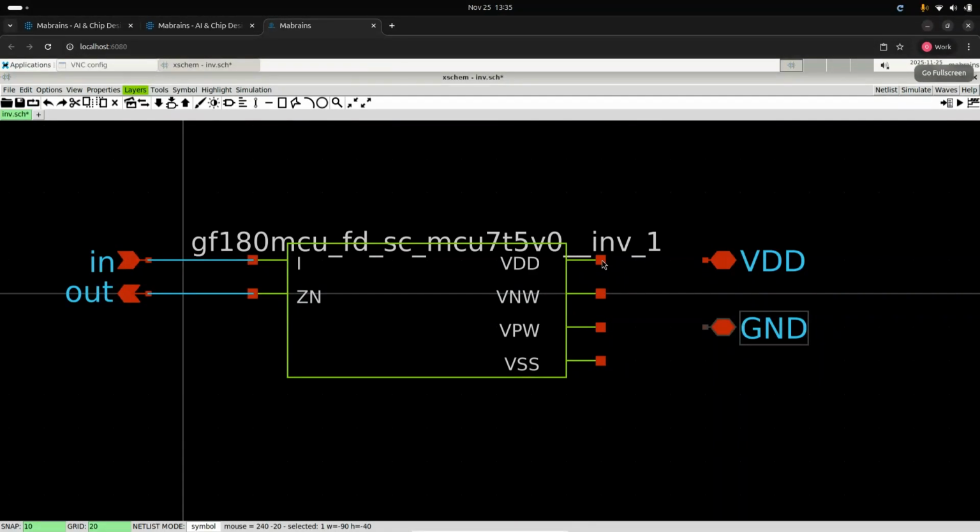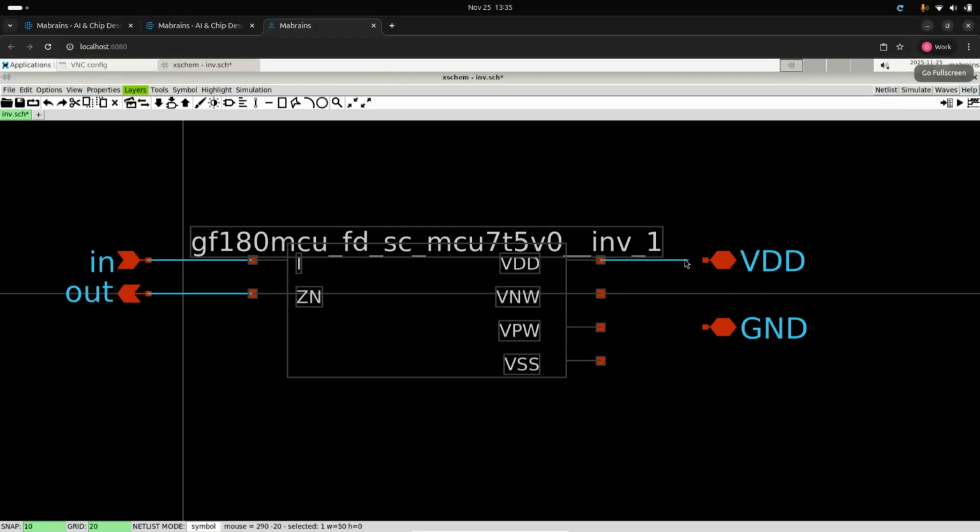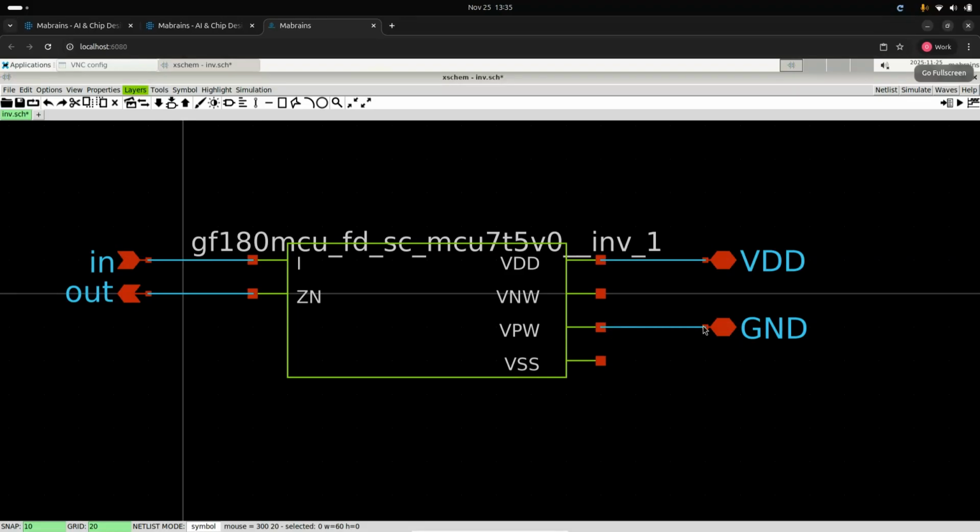And we wire those. So we press W here again, and we also connect the ground here, W here again. This will also be connected to VDD, so we can connect it like that. Press W and move up again. Press W, now they are connected. We also connect this to the ground, so W here, move up again, and press W. So this is our inverter schematic.